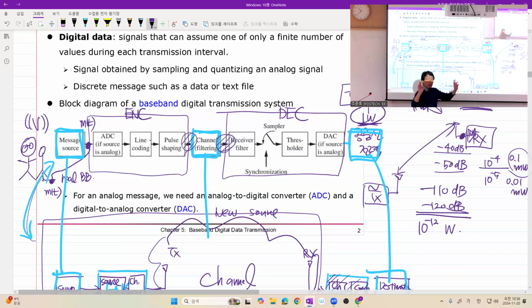But you need some interface between the digital and analog world. They are here, the A to D converter and the D to A converter. So what you do is that after you receive the radio wave and convert it using the antenna to an electrical signal, you just sample and quantize, so that you have what? A sequence of bits. And then you use a digital system. It may be some embedded system or some dedicated digital filter.